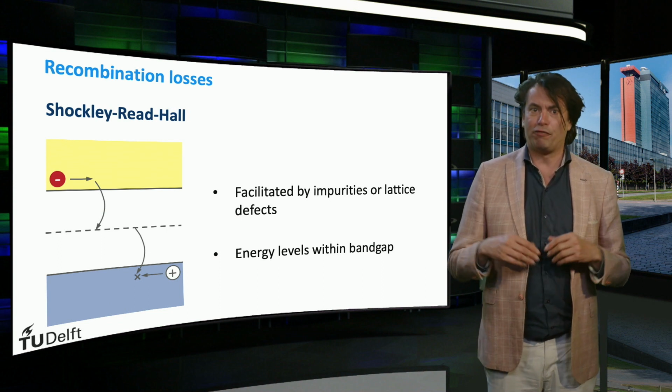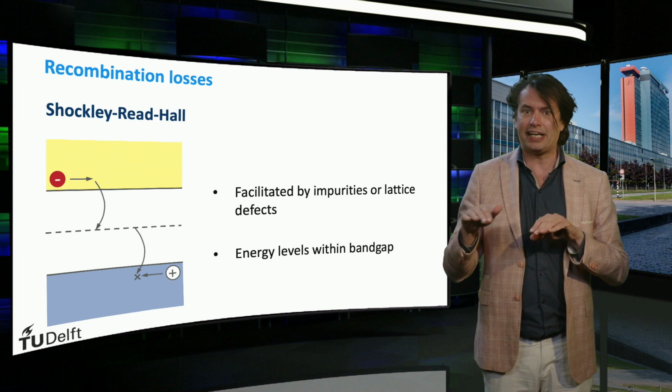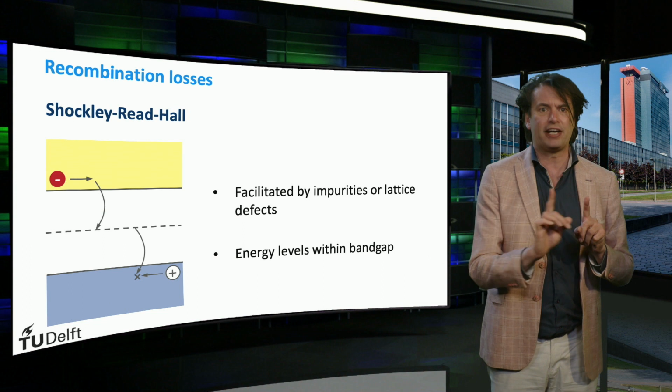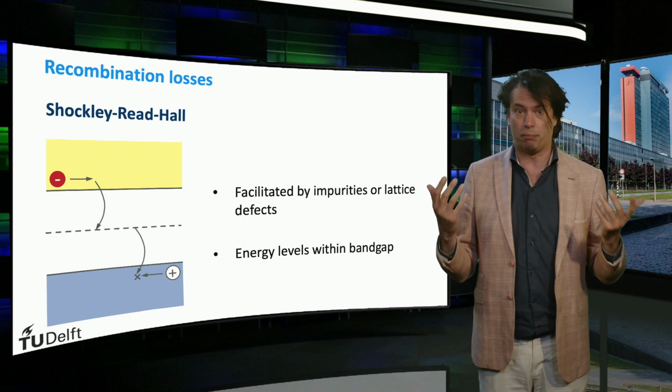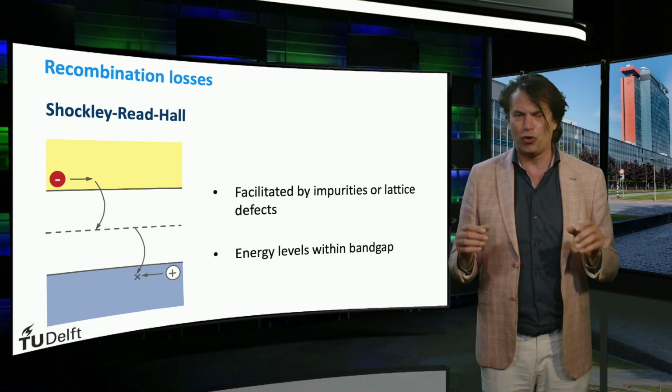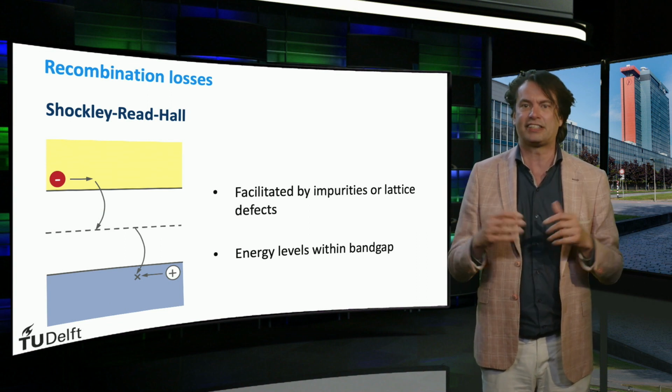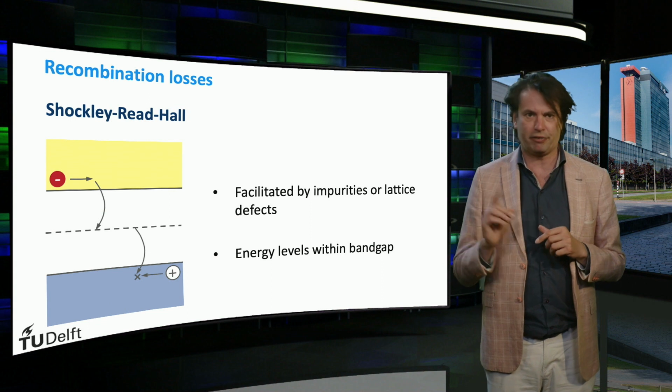At the surface of a semiconductor, the crystalline silicon lattice terminates. Therefore, many valence electrons cannot find a partner for creating a covalent bond. This results in so-called dangling bonds, which in essence are localized defects that may trap a charge carrier.